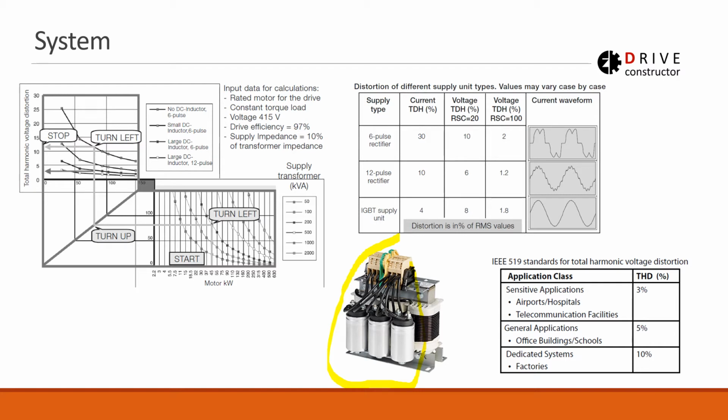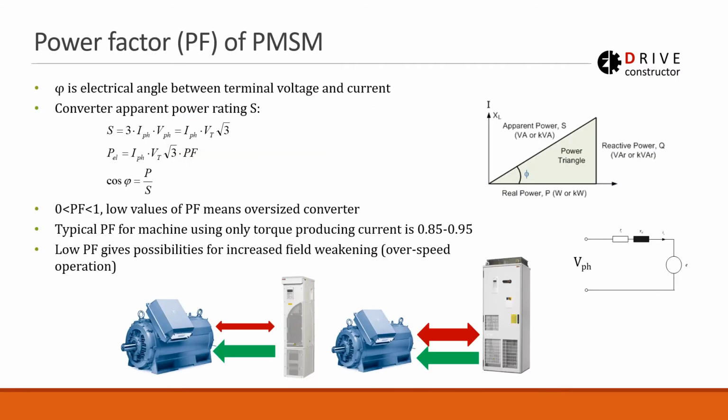Frequency converters are quite dangerous for both what is before them and after them, the grid and the electric machine, because frequency converters are switching devices, so they produce spikes of voltages and currents in both directions. So this should be taken into account. There can be quite interesting aspects and trade-offs in system design, and we'll now look into one of them.